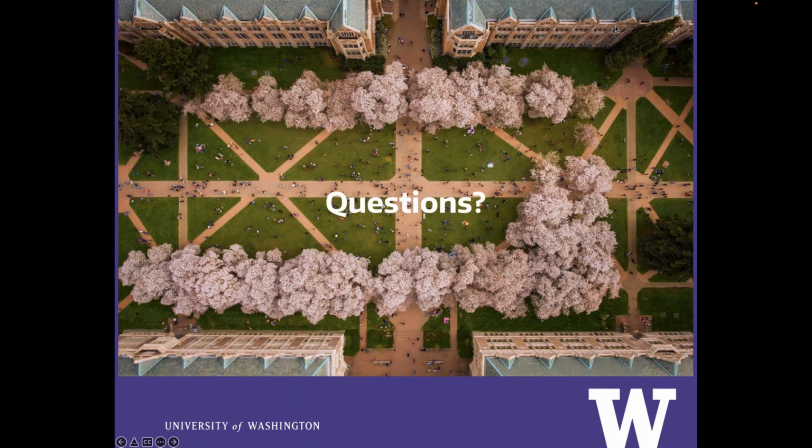In any of those cases where the engineer, contractor, and owner do not want any damage within the pile, I think the ring, which can be prefabricated and placed a little bit down, helps so that we're not over-damaging the cover, and in terms of driving forces we don't want it at the top. We're worried about that in terms of constructability.